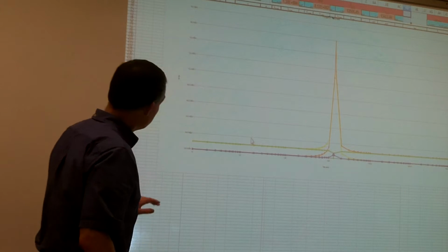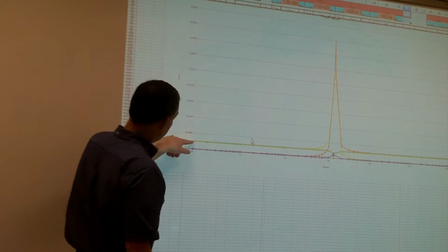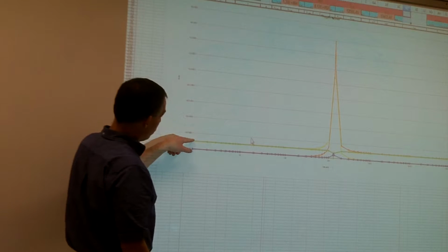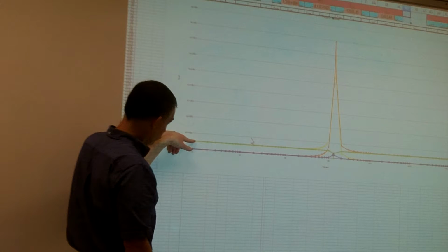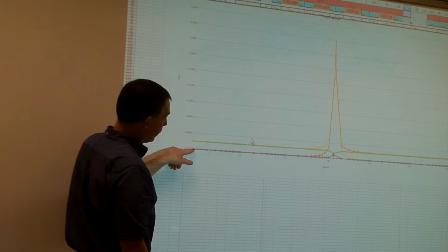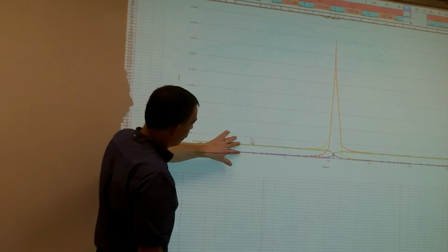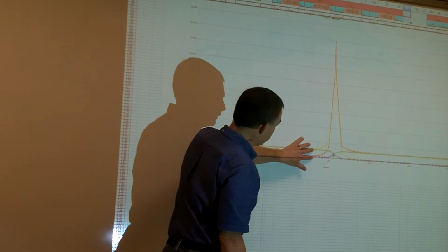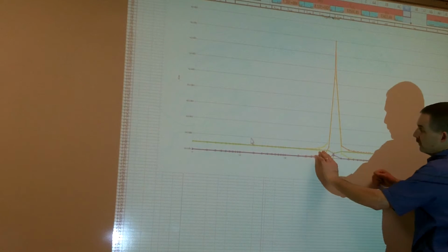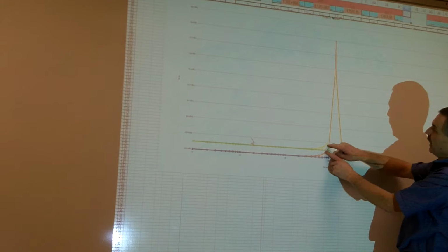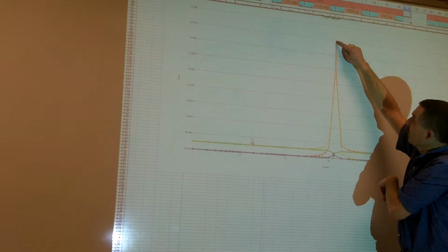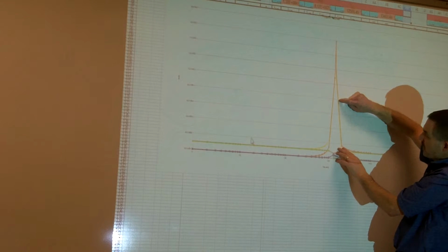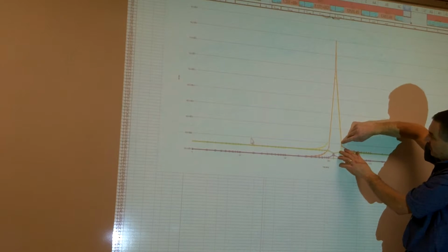Yep. So again, you can kind of see, here's my XC, or my VC, that's going to be equal to my source voltage. My VL is going to be very low, and those two are just going to go along, and nothing happens to them until all of a sudden I get right to my resonating frequency, and then VL and VC are both going to spike up really high, and then they're going to both start coming down on the other side of my bandwidth, and they're going to start to drop.